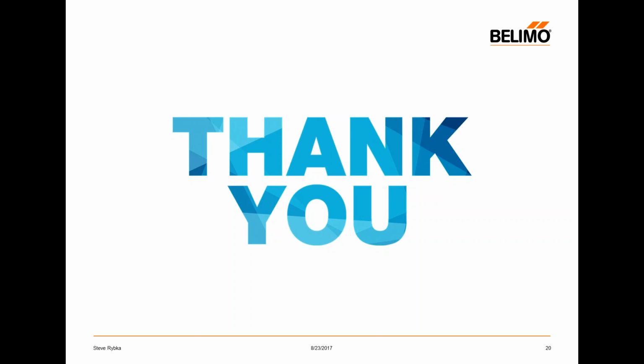Okay. Does the energy valve override the control signal from the building management system? To say it fully overrides it, it repositions the valve. So it's always reading that signal from the control system, but it will reposition it to a degree to slow the water flow down and raise the differential temperature. However, it does know that you have a specific request coming from that system, and it doesn't completely just close the valve arbitrarily. It keeps all the factors in mind while it's repositioning to make the coil as efficient as possible and raise the delta T without compromising temperature.